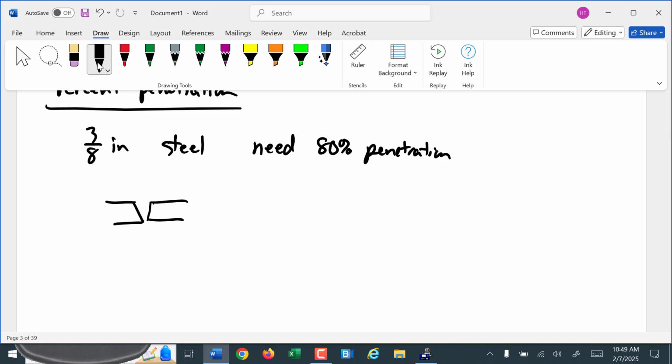So if you're welding two pieces together, best practice is to have the ends slightly beveled. Leave a small foot between the bottom pieces of the points. And then your weld would penetrate into the metal a certain percentage of the thickness. You don't want it to come out the bottom or it'll bubble the bottom. Ideally it would be 100% penetration with nothing pushing through.